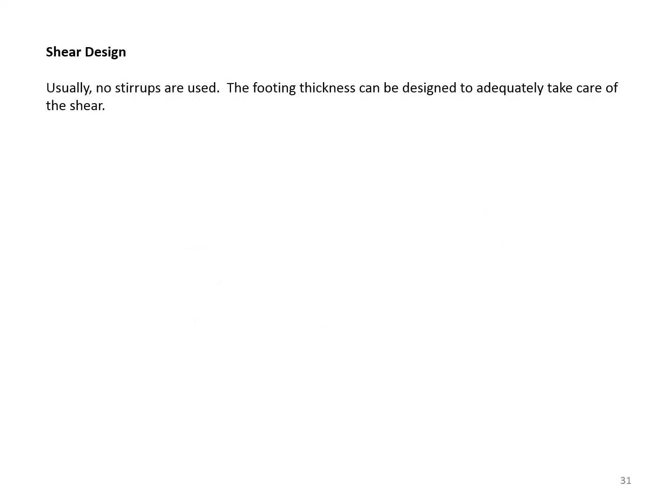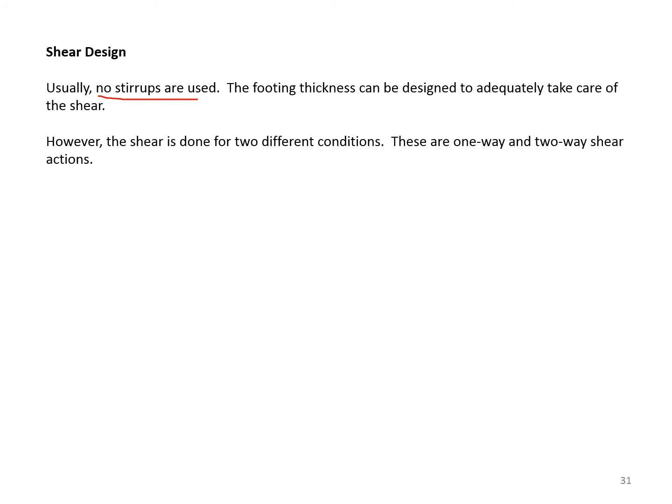For shear design, usually no stirrups are used. The footing thickness can be designed to adequately take care of the shear. However, the shear is done for two different conditions. These are called the one-way and two-way shear actions.